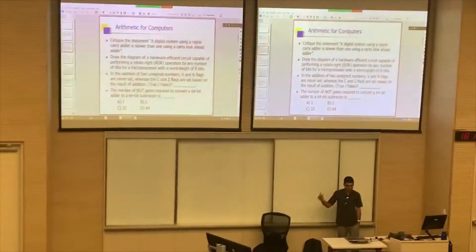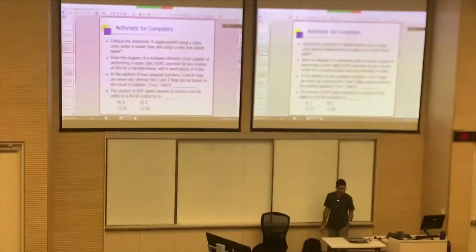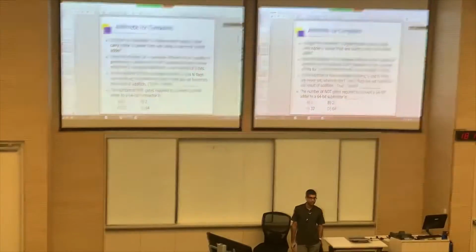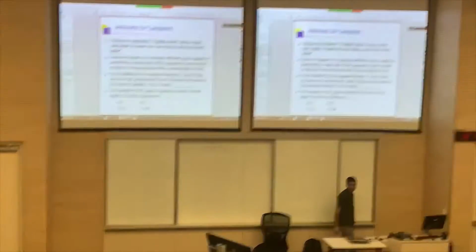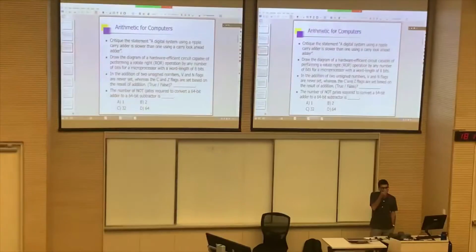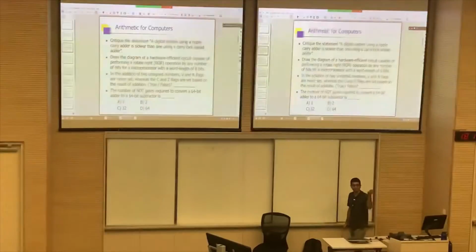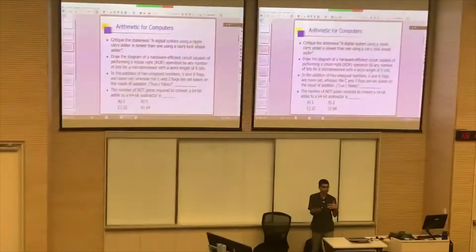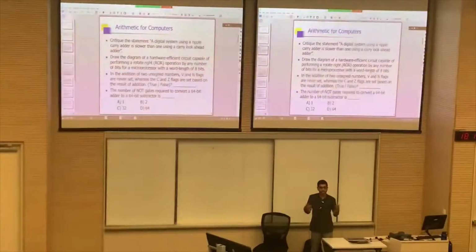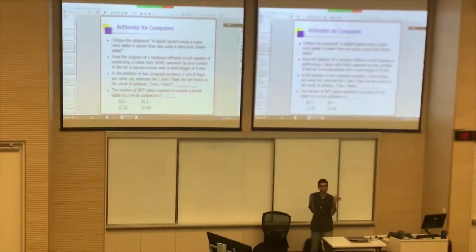Now, critique the statement: a system using a ripple carry adder is slower than one using a carry look ahead adder. Is it a statement that is categorically true? Not quite, right? We were just discussing that depending on the timing specifications, the synthesis tool or even the designer himself or herself might throw in more hardware to make it more performance oriented if the timing constraints are stringent.